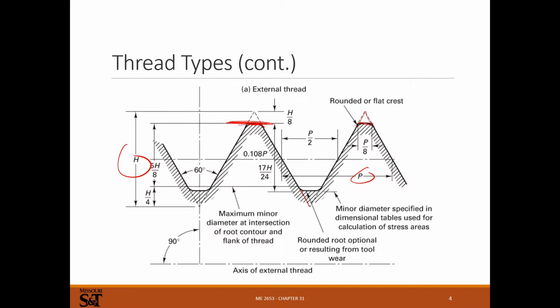Likewise, you really don't want to rely on this being down to a sharp point down there, because it's hard to machine, because you need a tool with an infinitely small radius right there, and that's not going to work. So we're going to truncate the bottom of the thread a little bit too, and so the threads are going to engage. There's going to be some minimum point down here, h/4 in this case, where we don't engage past that for unified threads. And you can see why this had to be standardized, because if you had something that followed this profile, but then you're threading something on it that required going down in this area, you're going to get interference and bad things. So that's why we had to standardize all this, so fasteners could be sold and interchanged.